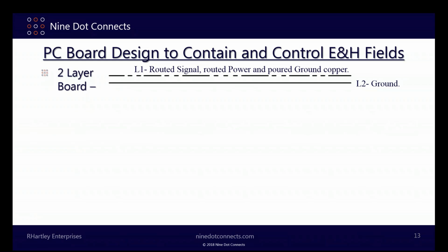By the way, I hope all of you are aware that when you're dealing with analog circuits, you do not need a power plane. Power for all analog circuits, regardless of frequency, can be routed, because the way power is taken into the IC to drive analog signals uses a filter that's designed to resonate at the frequency of the device. You don't need power planes to distribute power on the analog side of the board. Just making you aware of that.